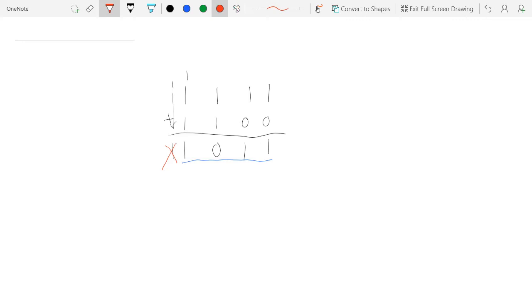And the CPU, the ALU portion of our CPU, it'll be doing the same thing. It's no different. It's going to give us this exact same answer if we were to feed it these two numbers. If I were to feed it these two numbers in my ALU, and I can actually hold on to this example and try it later and show you, we'll get an overflow. An overflow will occur. So anytime we try to do 4-bit numbers in 4-bit addition, and we get 5 bits out of it, we know that that's an overflow, and we're doing this math by hand.